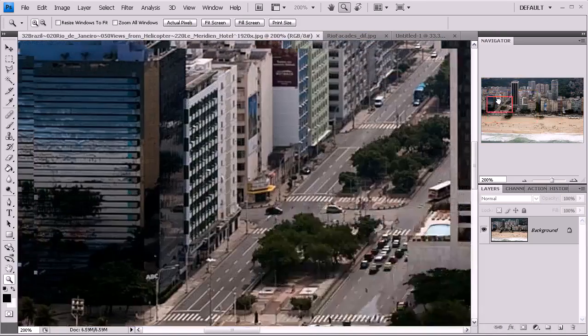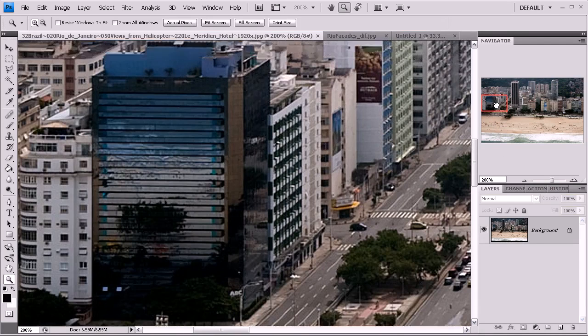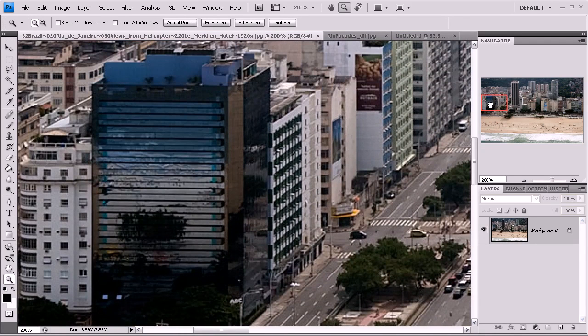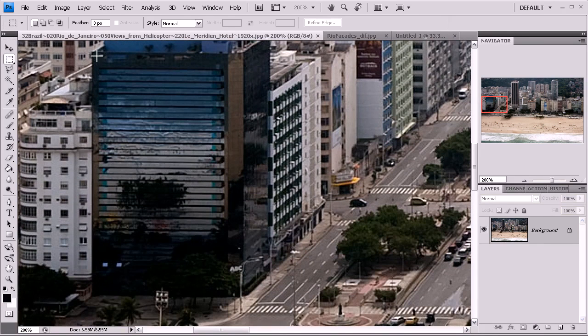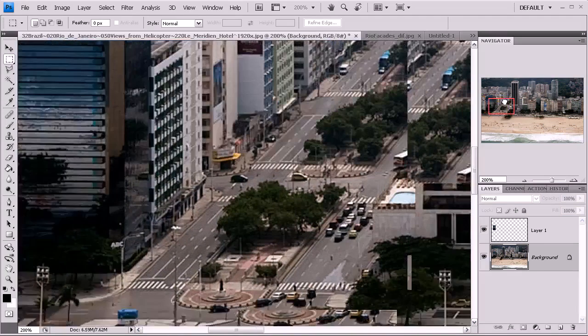Now what we want to do here is start on the one side and go and select each of the facades that we think we can use. I'm going to use only the ones that are in the front line. I'm not going to use any skewed perspective views, and I'm just going to take the square selection tool and select the facade. The ones that I do like, perhaps just that part there. Then I'm going to press Ctrl C, then immediately Ctrl V, and that's going to create that small extra layer for me. Then I go back to my original background and I can pan across,